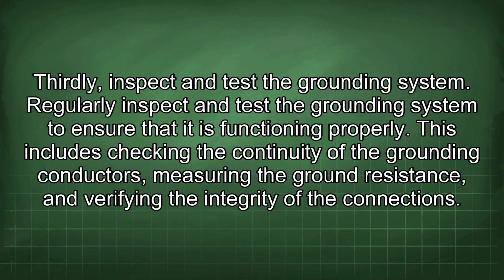Thirdly, inspect and test the grounding system. Regularly inspect and test the grounding system to ensure that it is functioning properly. This includes checking the continuity of the grounding conductors, measuring the ground resistance, and verifying the integrity of the connections.